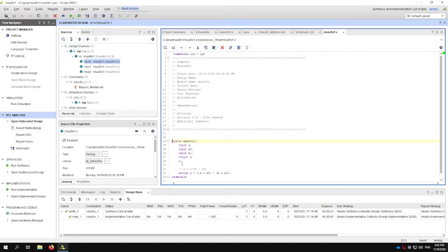I can kind of fake it a little bit. In Verilog, I can have what's called procedural programming. Again, I'm going to contrast procedural with concurrent. Concurrent is where everything's happening all at once in parallel, and procedural is where the order in which I assign values to signals very much matters.